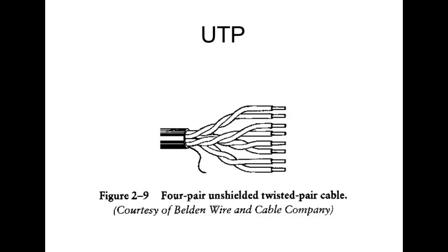If you ground it on both sides, it's going to be impossible for those two sides to be at exactly the same ground potential, which means now you turn a shield into a conductor, which is what they do on coaxial cable. It still has a pretty good function as far as keeping noise in and keeping noise out, but a true shield is only grounded on one side.